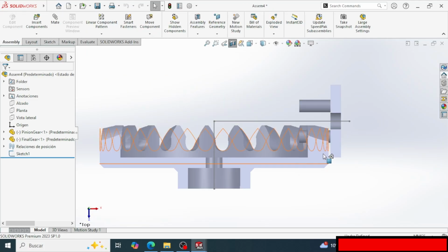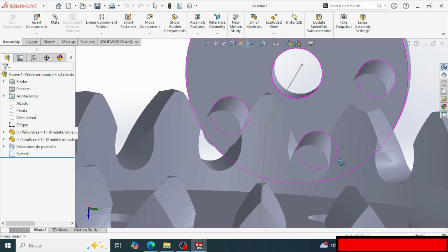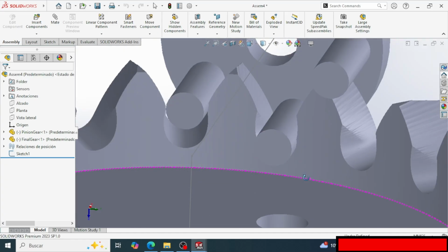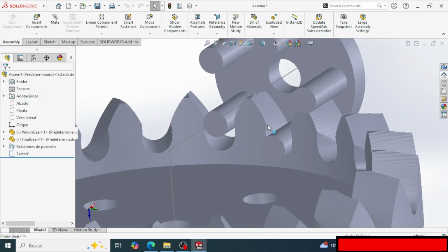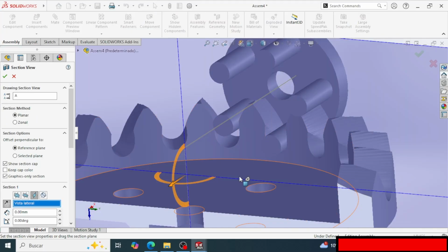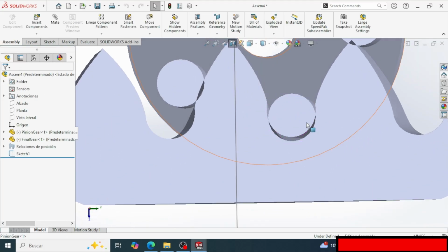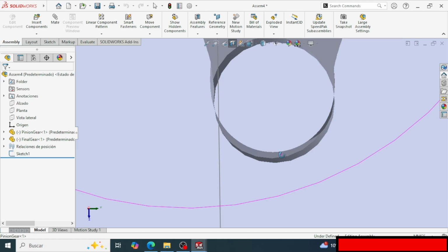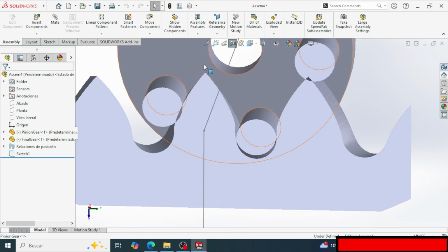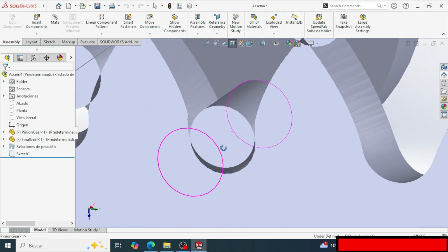We can reconstruct, and as you can see, the roller is in the correct position, just where we want it. Okay, maybe the clearance was a bit too much, 2 millimeters, I don't remember if we set 2 millimeters or 1.5 millimeters.